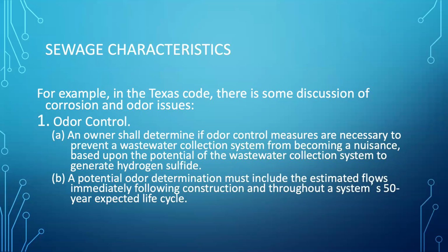So in addition to carrying sewage, these pipes also contain air. And with a little bit of creativity, and it's not something that's in any of our textbooks, but if they're designed well, it's possible to get the sewer to actually draw air into it and discharge the air at the treatment plant where you don't care if it stinks. And so basically that moves the odor.